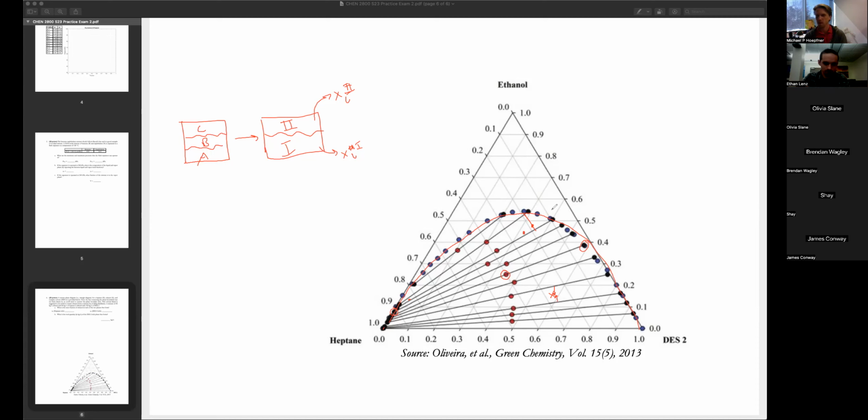Yep, good. And then on this one here, the last little thing is you kind of have to interpolate between these points here as well, right? Because it's almost exactly the same thing as how you're plotting PXY and TXY diagrams. So you're choosing 5%, 10%, 15%, and then you're connecting all of those with lines. And that's how you're plotting it. So it's the same idea, but they're doing it in the laboratory, actually measuring the compositions of the two phases.